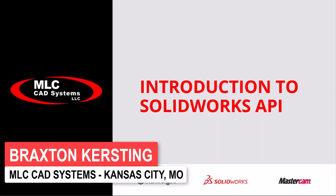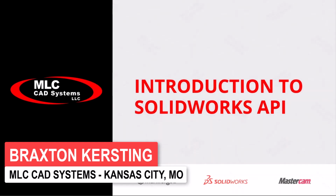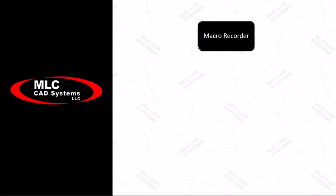Today we're going to be building some basic macros and getting familiar with the tools that we can use to help us develop our own custom macros. Starting off with the macro recorder. The macro recorder will allow us to record specific commands within SOLIDWORKS and produce the code to automate those commands.